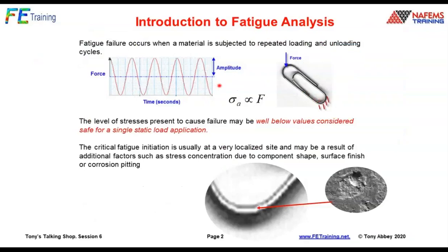So the idea is this is a cyclic load. And if we say that the force is proportional to the stress, that's the basic idea of uniaxial loading. It's related back to testing, where we have a uniaxial specimen where the force is proportional to the local stress. Now we can have a stress concentration factor in here, a geometric concentration factor, maybe due to the curvature here. But basically there's something causing that fatigue to start.